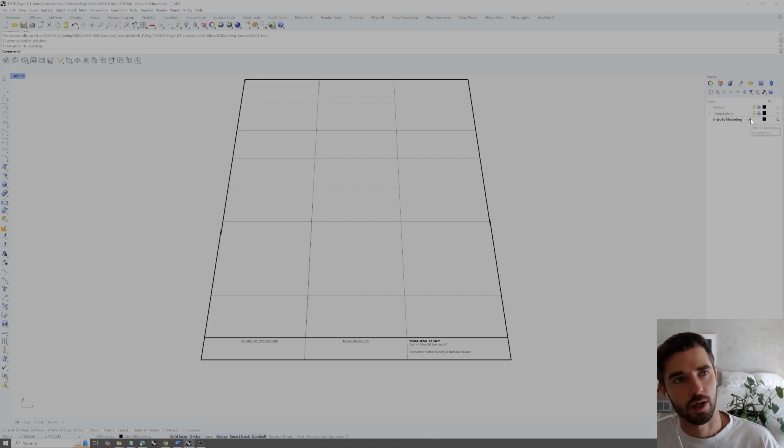The check mark is on, meaning that is our current layer, so if we make any geometry, it will apply to that layer. You cannot lock or turn off your current layer, so just keep that in mind. And even if you are activated on a sublayer, a layer under here, which we'll make in a moment, you cannot turn off or lock a layer that controls or is above that sublayer. So to make a sublayer, we just go up to the top here in the Layers tab and click New Sublayer, and we can just call this Step 1.